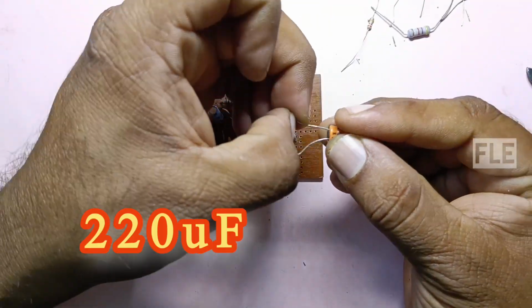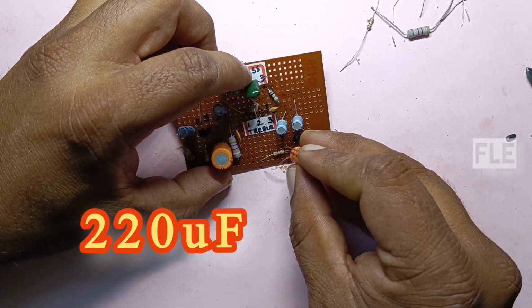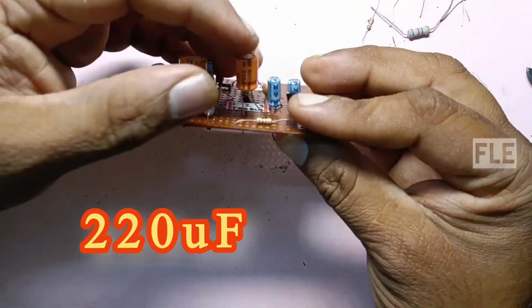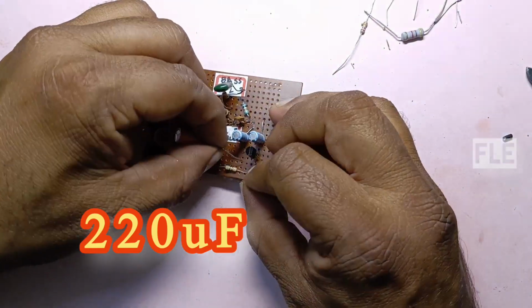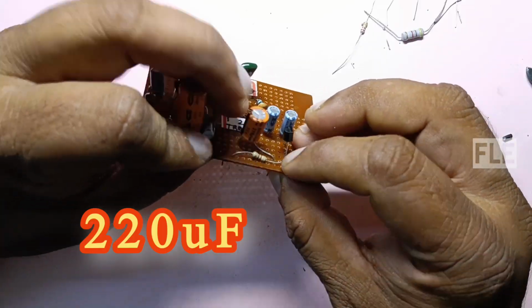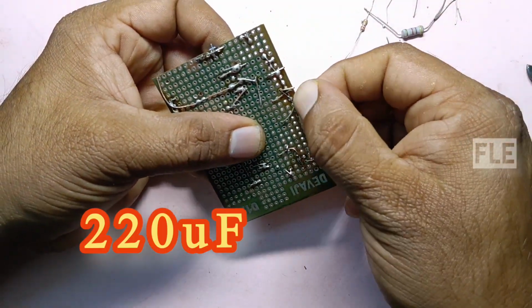Connect a 220 microfarad capacitor between the emitter and ground terminal. The 220 microfarad positive terminal is connected to the emitter terminal of the second C1815 transistor and the negative terminal is connected to ground.